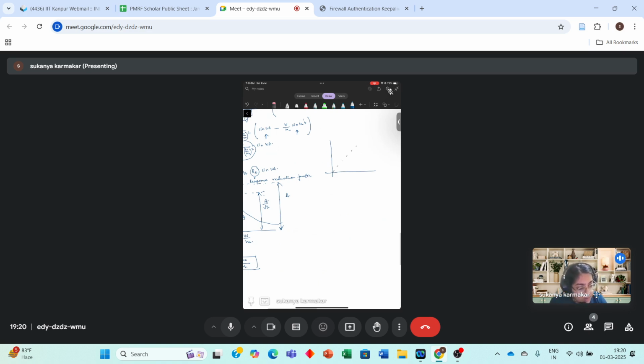So what we do, suppose under a given earthquake excitation, we know that this is the force F and this is the deformation, let's say this being delta, this is expected. Instead of designing for this force, you reduce this force by a certain quantity, and the factor by which you reduce is this response reduction factor. And this F is the base shear which I'm talking about. Instead of designing for a base shear F, where F is the base shear required if the structure has to remain linear elastic.